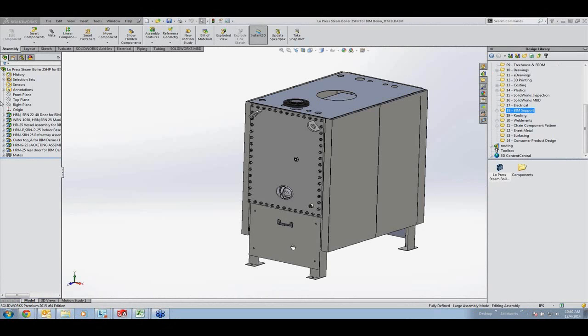Now when creating a sketched bend, we can see a preview of what the sketched bend will look like. Makes it easier than ever to create our sketched bends. You can select a fixed face here. You can see that it shows a little bit of a preview here. Okay, I can easily determine that that's not how I want this to look. So I'm going to change the angle here, and it will update the preview.